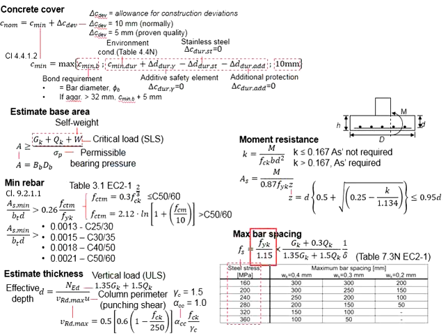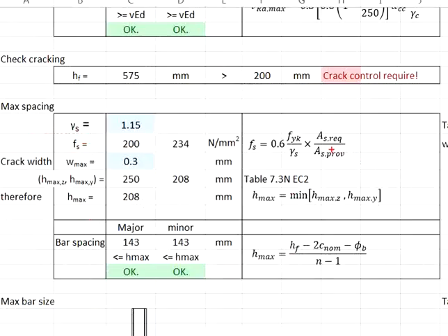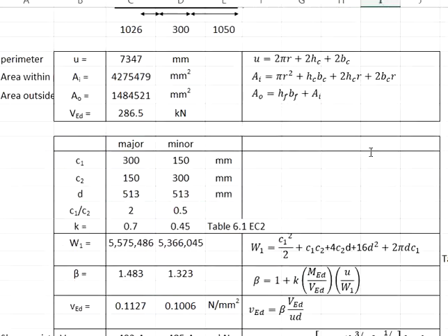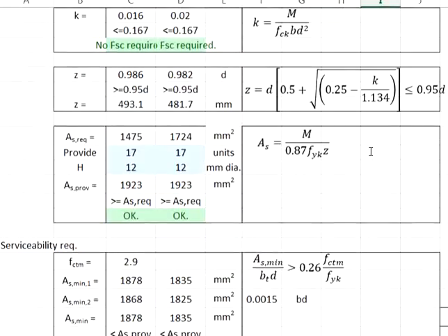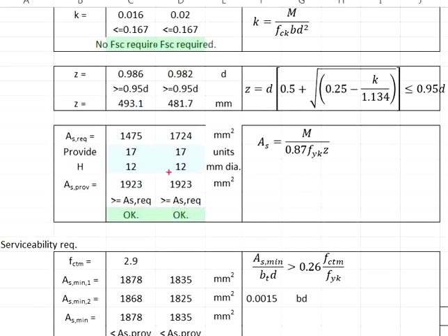And then multiply the ratio between FYK divided by the partial factor of safety of the steel, which is 1.15, as reflected here. These equations also take into consideration the area provided. There is an additional ratio of AS required divided by AS provided. The AS required, you may refer to the solutions in terms of the design of the reinforcement. These are the AS required and this is the AS provided.